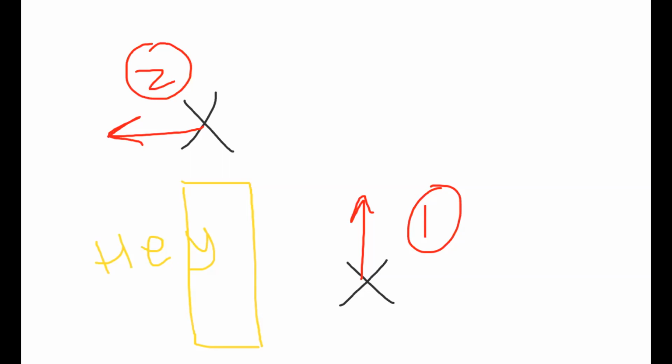And if it's basically bearing, to me, is a given in the program. Like if I have point 1 and point 2, and let's just, for the sake of it, say that's northwest and it's a 45-degree, it's perfectly northwest. The computer can figure that bearing out for me. So it's redundant for me to provide it, and it's a potential point of error if I have to provide that. So in that example, that's why I was saying, yeah, if I don't have to provide it, it's easier and less error prone.